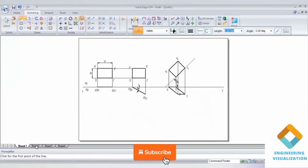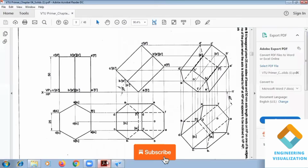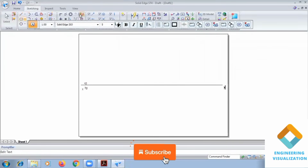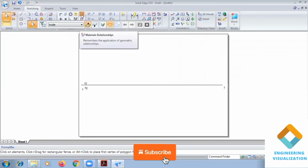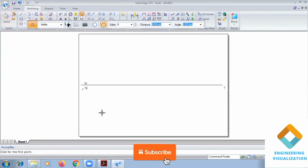Problem number 6, with respect to the edge here. So a hexagon of dimension 25. Make sure this icon, maintain relationship, has to be on. Then use polygon by center, 6 sides. Okay.